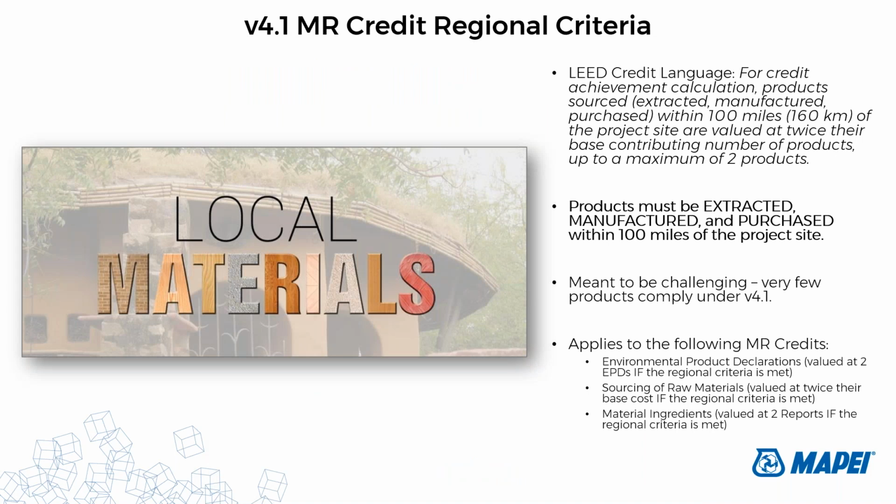Under past versions of LEED, there was a regional manufacturing credit. It was its own credit. Things changed under version 4. LEED version 4 or 4.1's local criteria changed. So products sourced, which means they're extracted, manufactured, and purchased within 100 miles of the project site, are valued at twice their base contributing cost or number of products, up to a max of 20% or 2 products. I promise I will explain what that means.